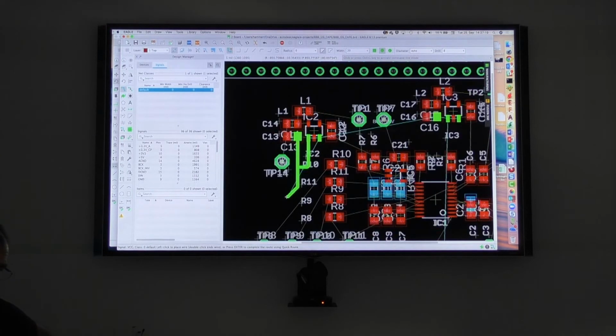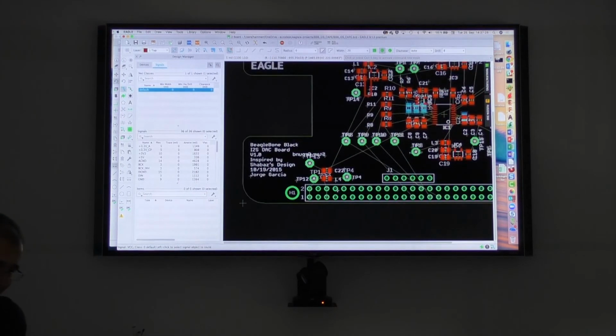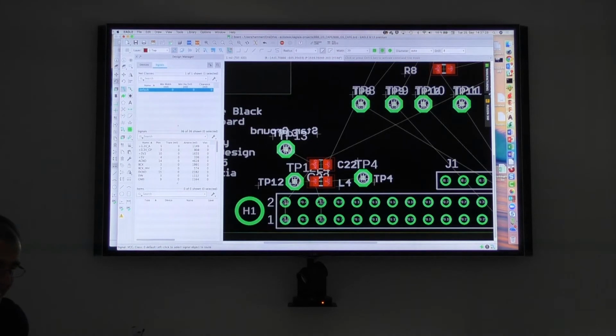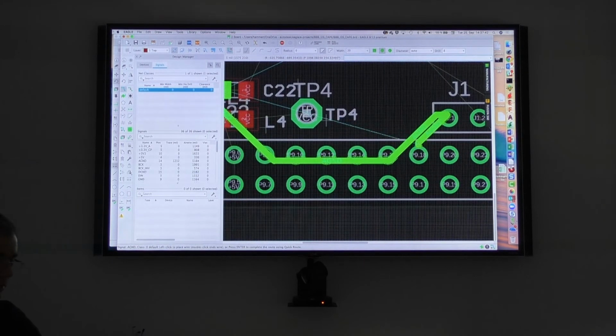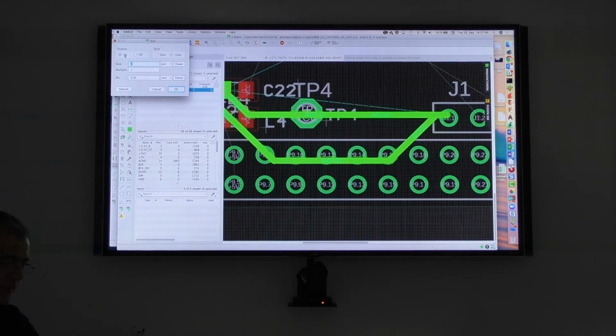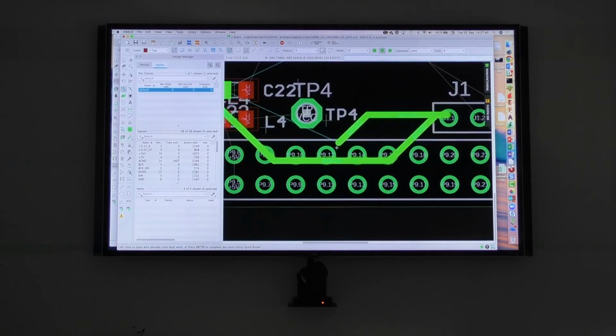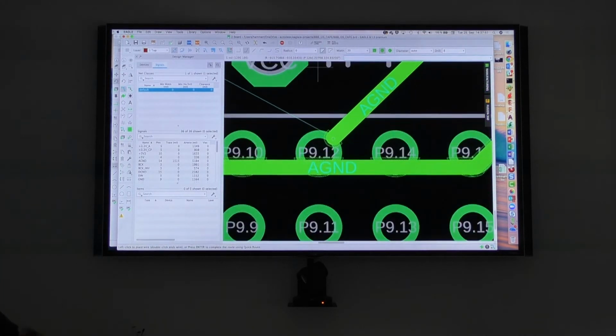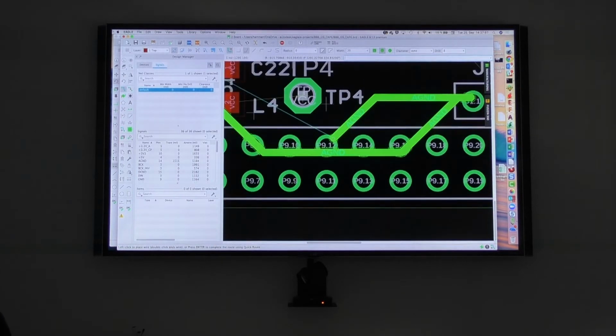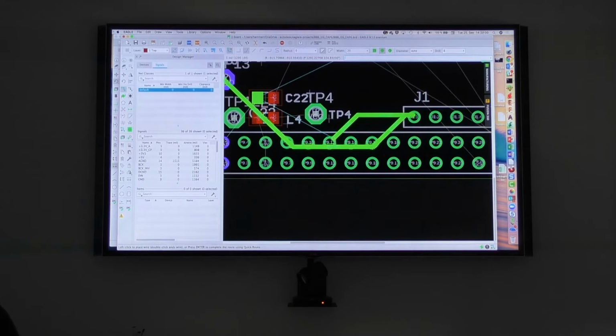Let's keep the 20. Go down anywhere. Okay, take another one. Let's start here, and that's what I can do directly. And in this mode, that's what I wanted to show you. You can do all the nonsense you can imagine. What you see is, if I switch off the grid, then you can see it better, that the design check immediately shows you some error polygons. It's the live DRC we have there. You can also switch it off, but that's an indication that there's something wrong.